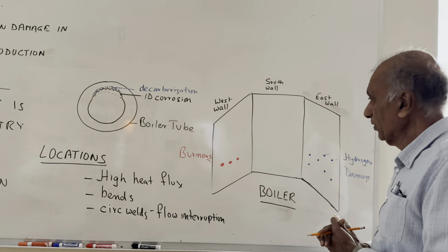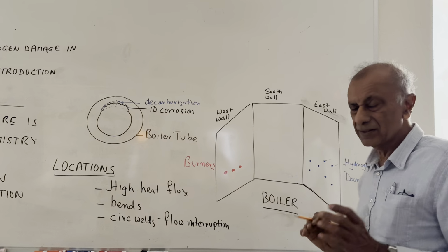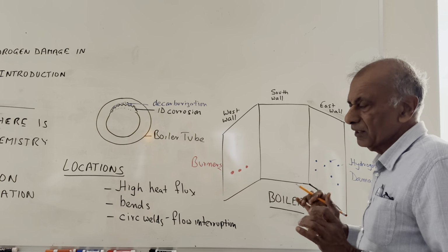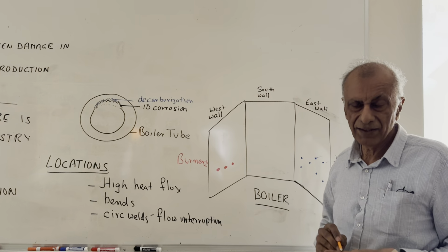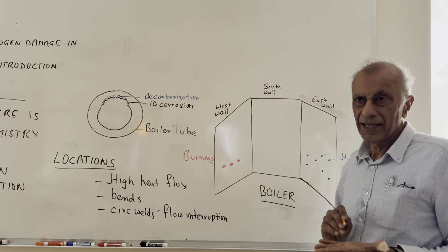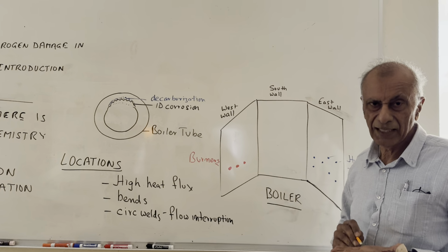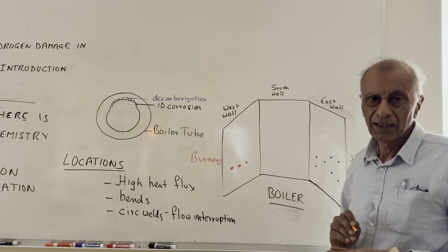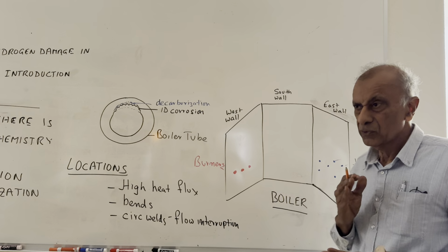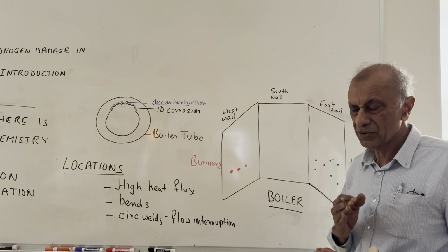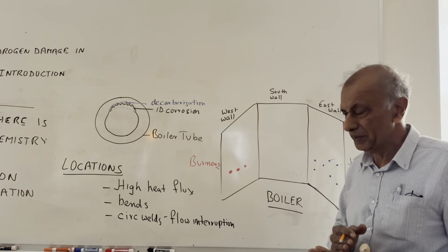In order to do this inspection, it's a very targeted inspection. First of all, you only do this inspection if you have already had a hydrogen damage failure, and you have verified the hydrogen damage by cutting the tube and sectioning it just the way I showed you, those 3 tube samples. You have to make sure that the failure was caused by hydrogen damage.